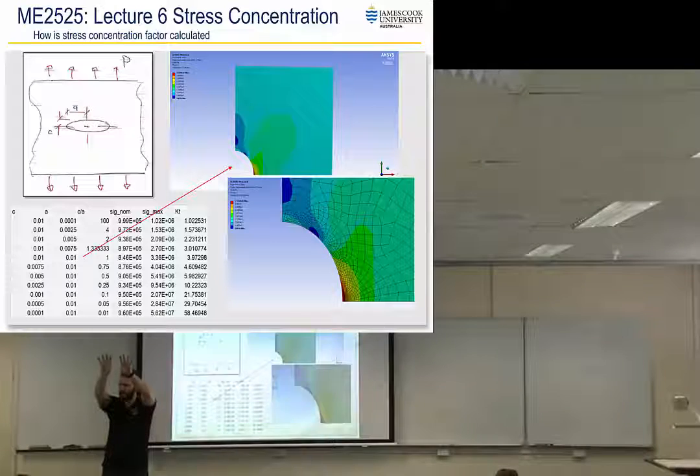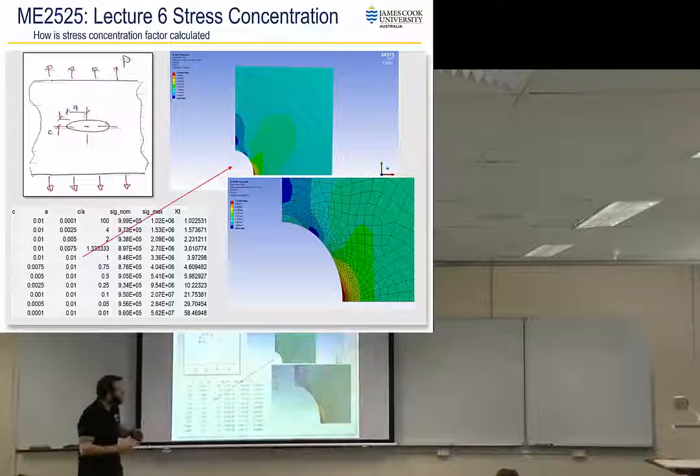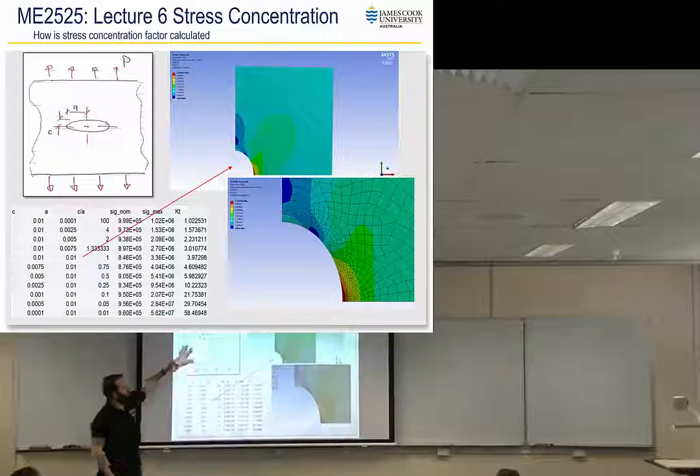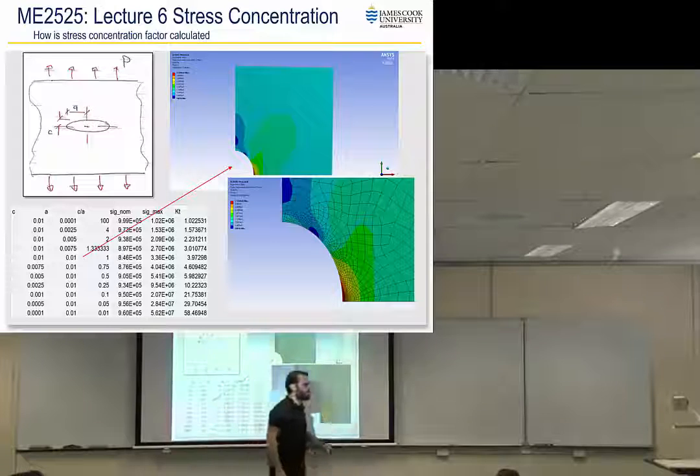All of the force is up and down. Now, it's not necessarily the case for other things like bending and that kind of stuff, shear, certainly. But a vertical slot has almost no effect, and if it's infinitesimally small, if it's literally just 2 pieces of material touching in the centre there, it shouldn't have any effect, and your stress concentration will be 1. Okay? And so that's an example just for a slot and a hole.